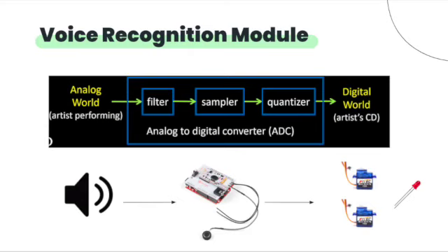The signal is then divided into small segments as short as a few hundredths of a second, which are then matched to known phonemes in English before being fed into the speech recognition program. This program examines the phonemes around each other and runs a complex statistical model to compare them to a large library of known words, phrases, and sentences. Then the program outputs what it believes the individual was saying as either text or, as in our case, a command for the robot that is checked to control the servos.